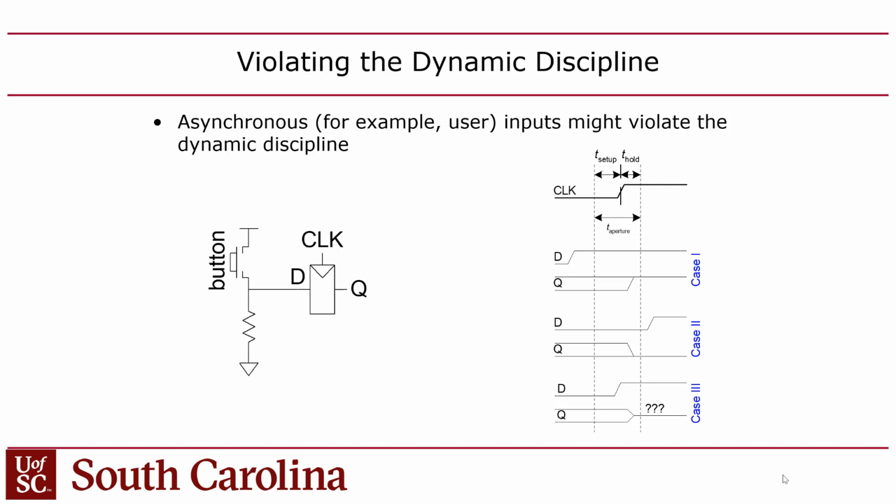But anyway, you might say, what about the skew? Where does that come from? Clock skew, I think that's part of the FPGA library that's built in. I think Quartus knows that because it knows what FPGA you're targeting. Actually, it's a combination of the FPGA plus the packaging, what kind of package it's in, the ceramic package. I don't know, it knows that somehow. I never really looked into it. But it knows what the clock skew is, and the clock speed is something that we give it with the QSF.